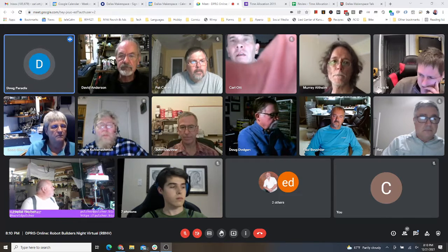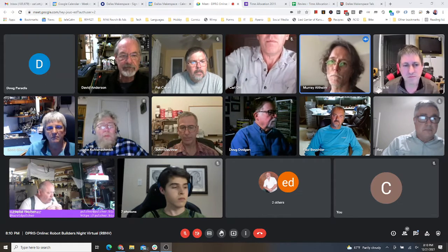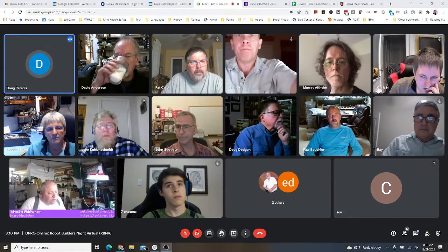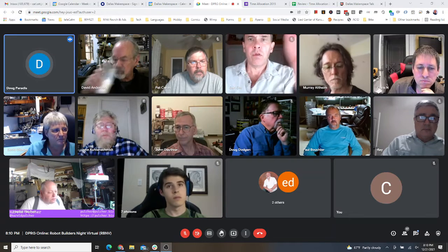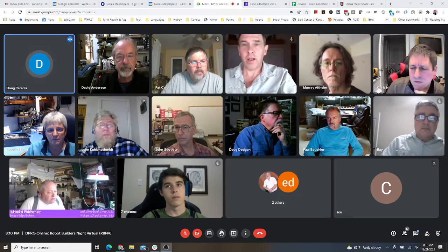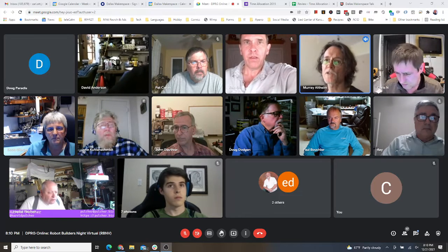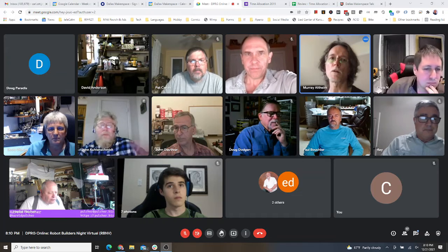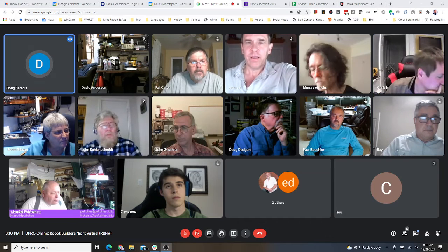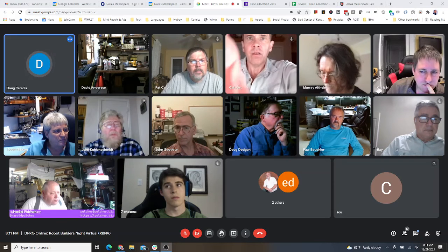Yeah, but Murray, is it an ST chip? It's an ST chip, just the chip itself, but the boards are made by SparkFun. Okay, but if it's an ST chip and it's got enough memory, I believe there is a MicroPython port to ST boards. But you have to have an image specific to the actual STM32 model. Is the model that you have one of the boards that's supported? Because I believe it's a big list of ST parts.